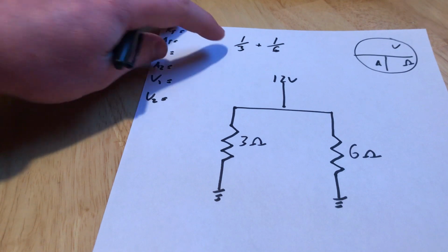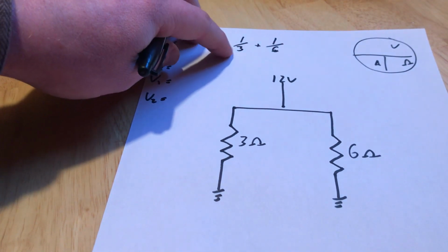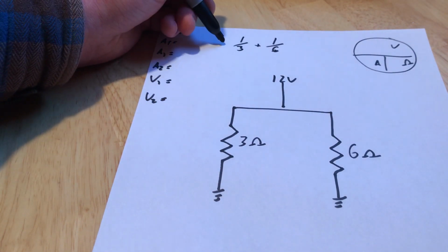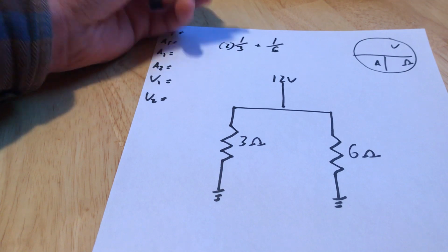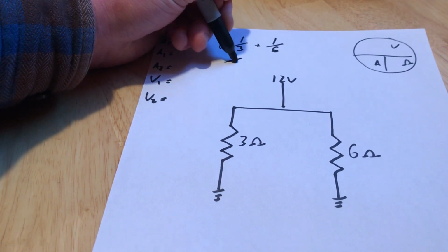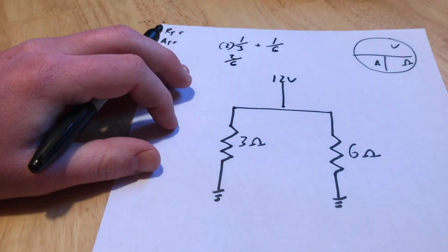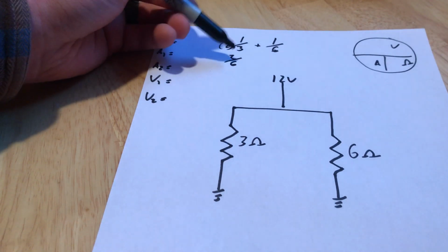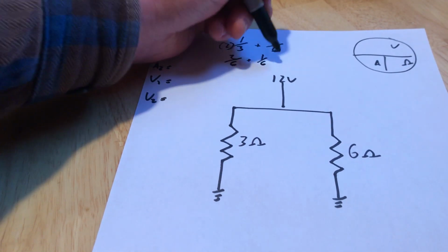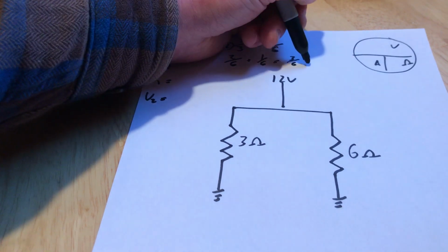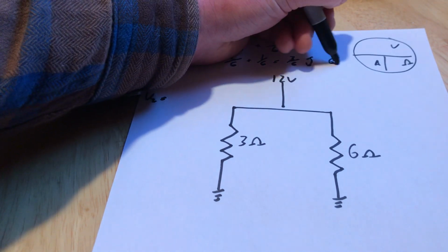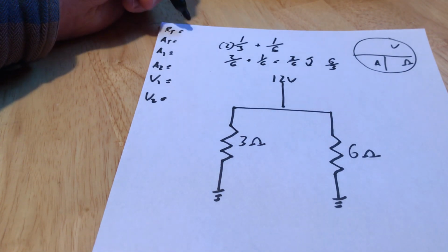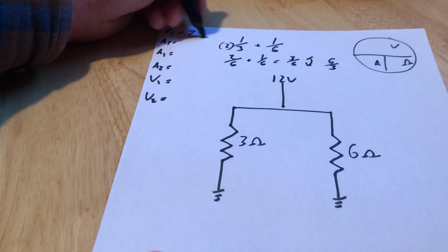Alright, so I need to make my denominators the same, and it looks like I could just double this one and get 6. So thank you, easy numbers. That makes life easy. So I'm going to multiply this whole fraction by 2. So 2/6 is the exact same thing as 1/3, right? 1/3 is just simplified all the way down. So 2/6 plus 1/6 equals 3/6. Have to find the reciprocal. So 6/3. Oh, that's easy. That is definitely 2. So my total circuit resistance is 2 ohms.